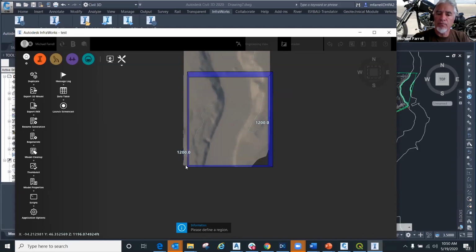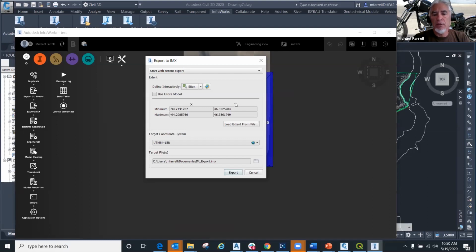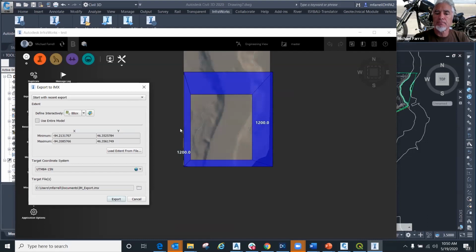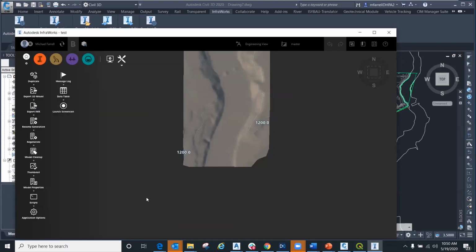And then when I've finished that, it's just going to give me that data within the bounding box. Right. Okay. So that also saves you, once you bring it into Civil 3D, from thinking, oh, I didn't want that much, so now let me put a boundary on it. You could essentially do that post-processing right inside Infraworks as you take the data out to Civil.